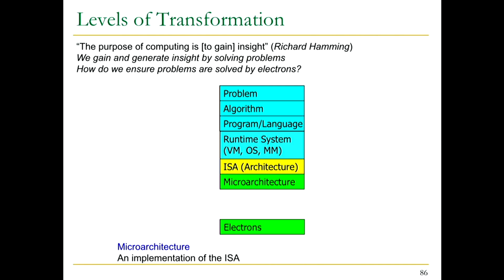For example, let's start with a simple add instruction. There are many, many ways of designing an adder, right? Let's say you're adding two 32-bit values. You can add all of the 32 bits in parallel, or you can add 1 bit every cycle. So you do it over 32 iterations. This has implications on your hardware.